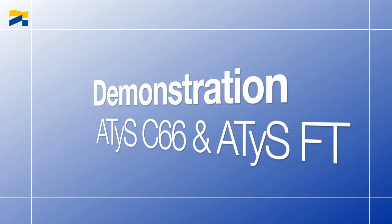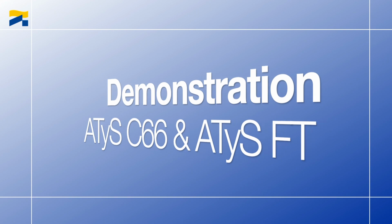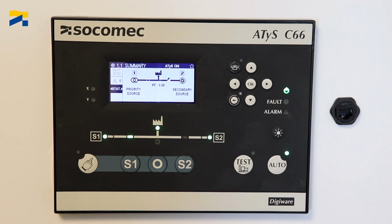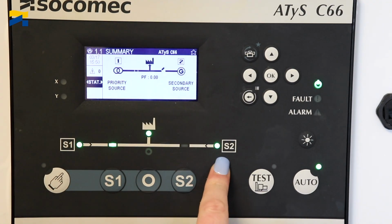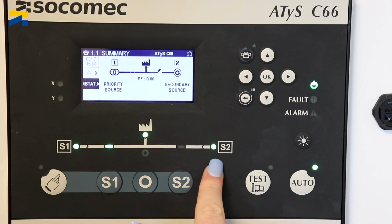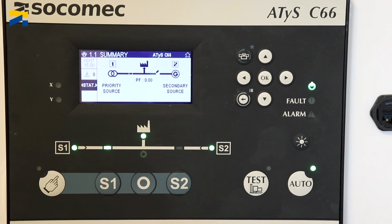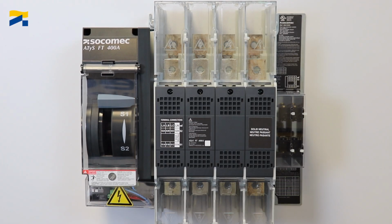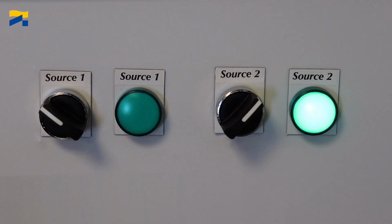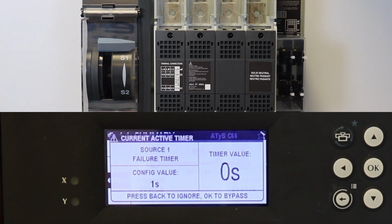Now that the configuration is complete, we will show how the ATyS FT works when a source is lost. Looking at the screen, you can see all the LEDs lit up. Based on these, we can see right now that source 1 and source 2 are available and that the source supplying the load is source 1. We can also see that the manual handle is on source 1. So when we switch off source 1, you will see the LED go out for source 1 and the timer will start.